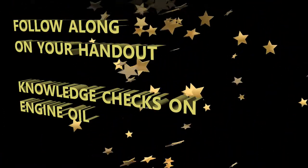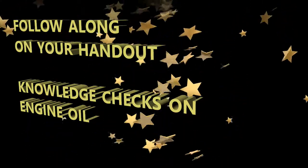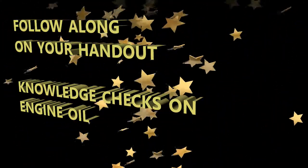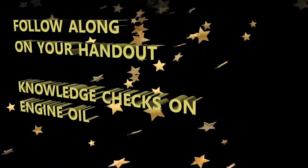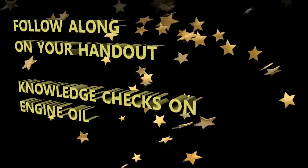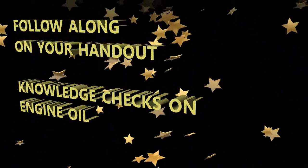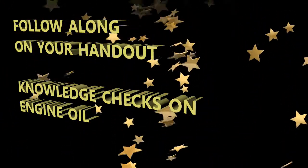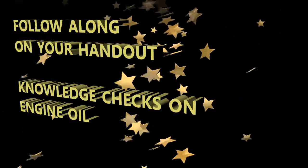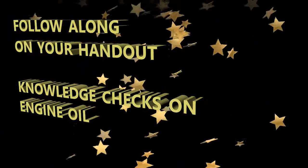Please take notes. 155 degrees Celsius is the same as 311 degrees Fahrenheit. Remember, the green light will come on at 284 degrees Fahrenheit, and if the temperature gets higher and higher, you're going to get to 311. That's the trigger where the amber light comes on, which automatically turns on the master caution light.